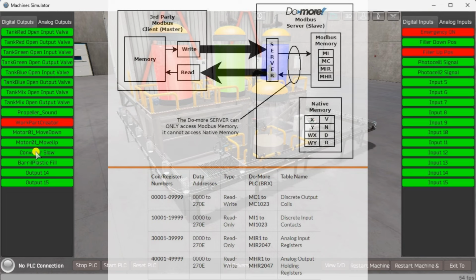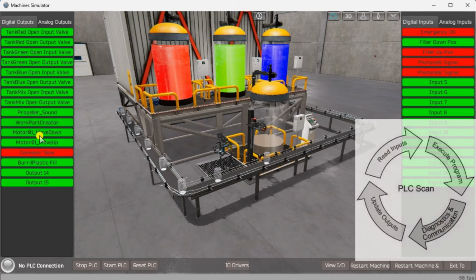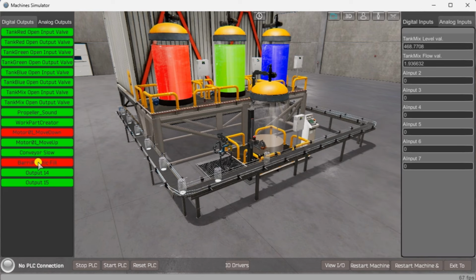It is important to note that PLC programs operate cyclically, meaning they continuously read the inputs and set the outputs. This ensures that the program is responsive to changes in the system and can adapt accordingly. By understanding the inputs and outputs and their relationship to the overall system, you can develop a logical sequence of operation for the ink mixer PLC program.